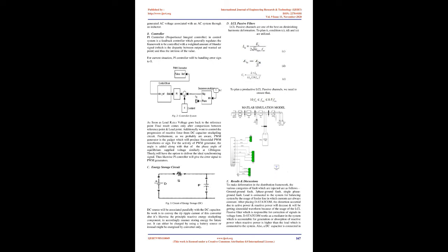A voltage source converter, VSC. A voltage source converter is power electronic equipment that is connected in parallel to the system. It may produce a sinusoidal voltage of any required magnitude, frequency, or phase angle. The VSC is used either to completely replace the voltage or to inject the missing voltages. It can also convert DC voltages across storage devices into a set of 3-phase AC output voltages. Moreover, the D-STATCOM is also able to generate or absorb reactive power.